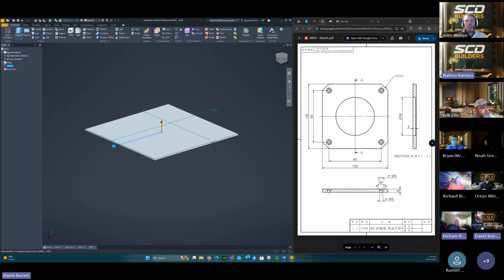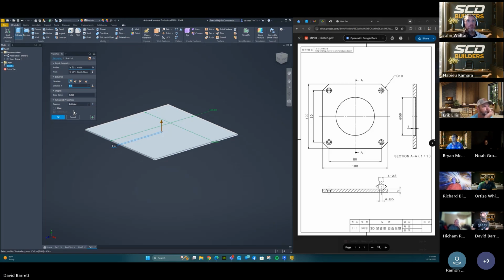And it's going to bring up this little tab right here. It's called the little properties tab for the extrude. So now what it's going to do by default, since you selected your sketch in the beginning and then you went extrude, it's already selected, so it's going to extrude. Right now it's extruding 1 inch, but we want to make sure it's going 5 inches instead.